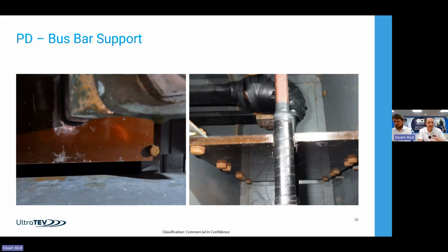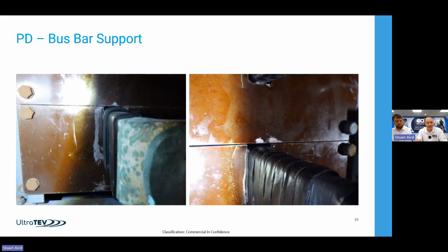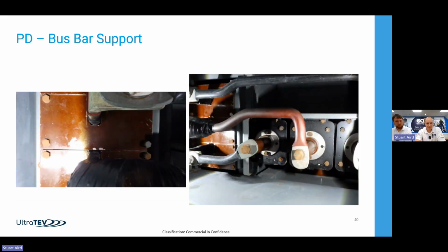And what that does is it starts to create this acidic atmosphere, similar to what we mentioned earlier. So we can see any of the nuts and bolts within there are all rusting away, and we see damage to all the supporting structure. As you can see, it's quite aged switchgear. It's been in for many years, but it's starting to fail now. And you see other ones. So this verdigris, this greening, is caused by the nitric acid on the copper work within there. And any little gaps, we see little white bits and damage around there as well.